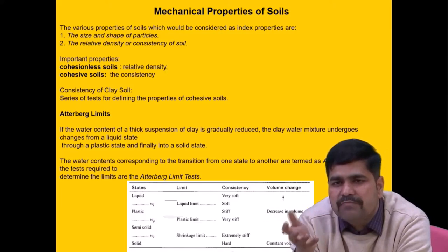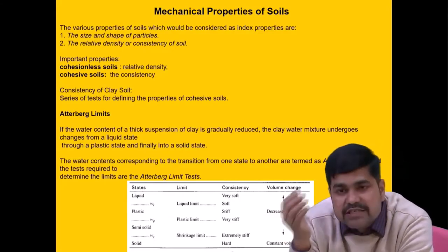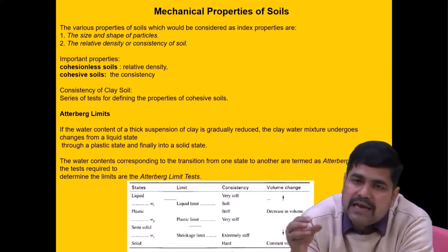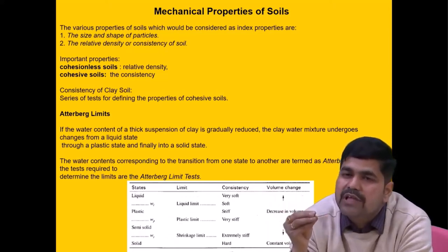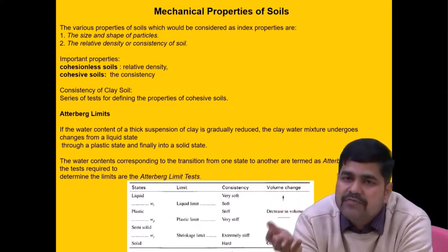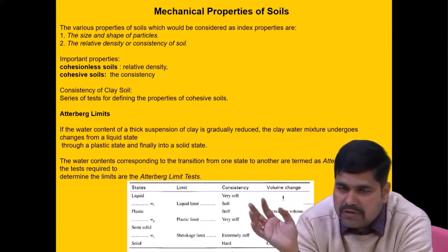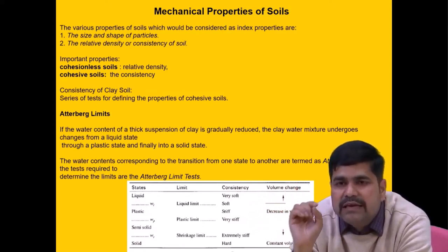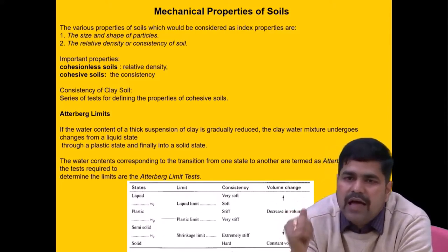So, in 5 minutes of heating we reach the liquid limit, another 5 minutes we reach the plastic limit, another 5 minutes we reach the shrinkage limit. That simply means the soil can get swelled up, or it can easily be dried up. That is dangerous for any infrastructural building that is going to be constructed on it. So, we have to be very careful and see keenly in how much duration my limits are happening.